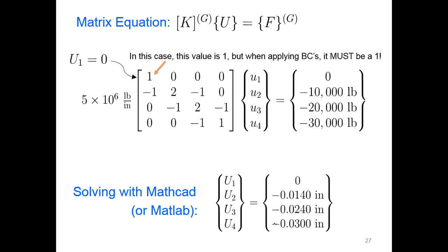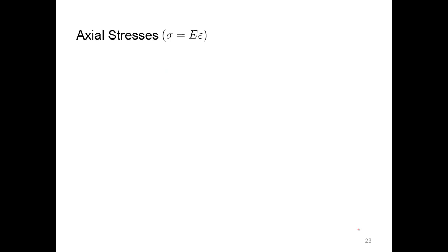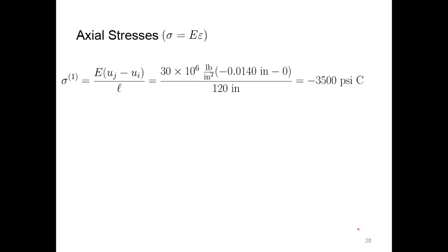So solving with MathCAD or MATLAB, we should come up with these deflections at our different nodes in our beam, or in our column, rather. All right, so let's look at our axial stresses now. So we've got the deflections. Let's go back and calculate the axial stress.